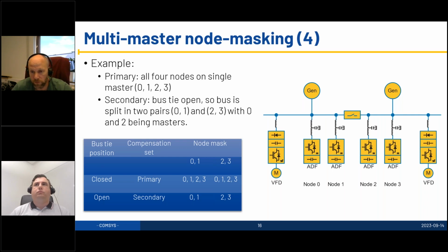The ADF is an inverter, so it's controlled by software. It has a peak current limitation, it has fuses, it has a runtime control limitation, and it will try to limit the damage when it sees that the current is rushing. It will open the contactor, it will disable the switching, and one of these mechanisms will come first and simply stop the output current.